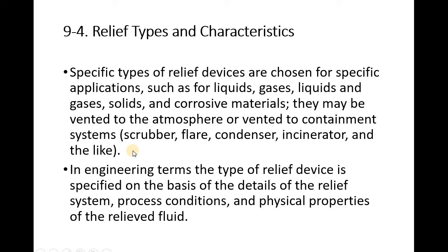I think it's a good example just to refresh where we can put our relief valves, and I think that sounds easy for most of you. So what are relief types and characteristics do we have? We have many types. Specific types of relief valves are chosen for specific applications, such as for liquids. So you are saying simply that relief types depend on whether it's a liquid, a gas, or a solid, a corrosive material, whether it is vented to the atmosphere or vented to a containment. There are many variables based on which we are going to identify the